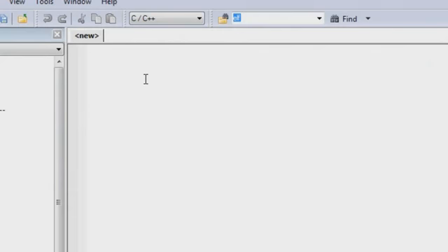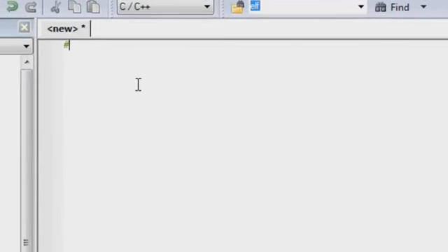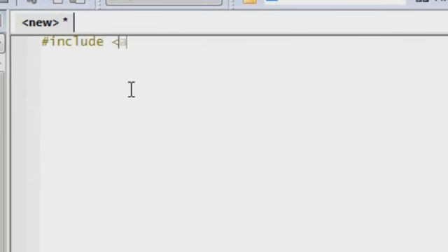The first line we're going to put in all of our programs is called the include statement for avr/io.h, which is a header file. .h files are called header files. The file that we're making right now is the .c file. The header file is added on to the beginning of the .c file that we're going to be creating. And it has a lot of code that we don't have to write that contains information and definitions for the AVR line of microcontrollers. Depending on the one we're using, it'll make those changes for us.